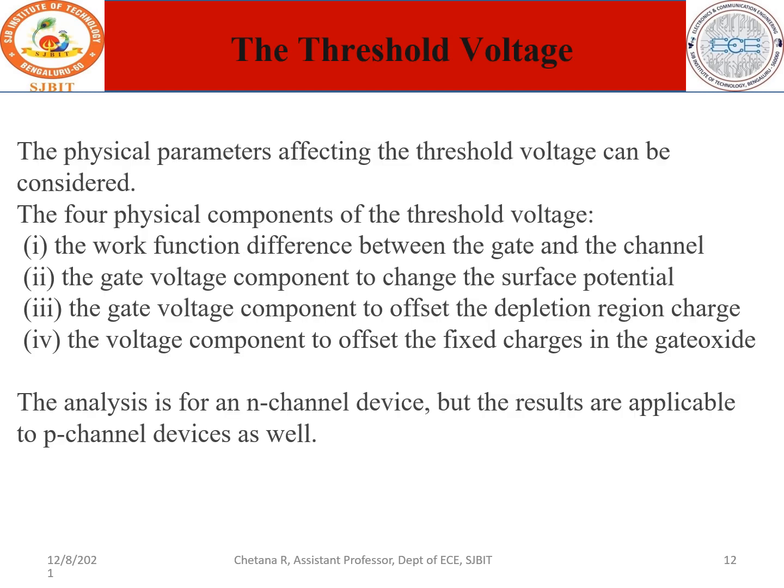So what is the threshold voltage? The threshold voltage parameters which are reliable are the work function difference between the gate and the channel. So the focus on first understanding the threshold voltage is that it is dependent on the work function difference between the gate and the channel. Because the channel is nothing but your diffusion material, either N type or P type, and the gate is made up of polysilicon.